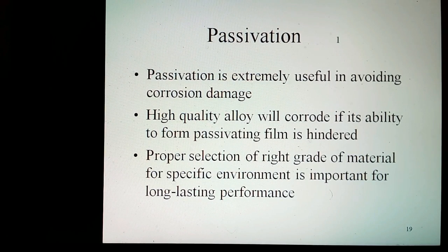Passivation is extremely useful in mitigating corrosion damage. However, even a high-quality alloy will corrode if its ability to form a passivating film is hindered. Proper selection of the right grade of material for the specific environment is important for the long-lasting performance of this group of materials.